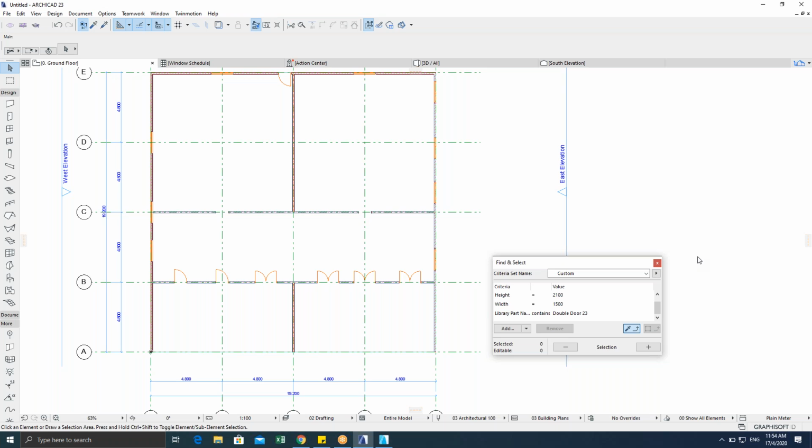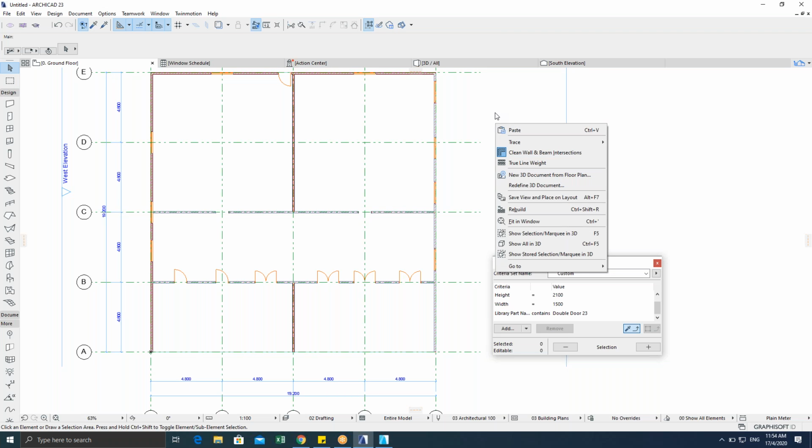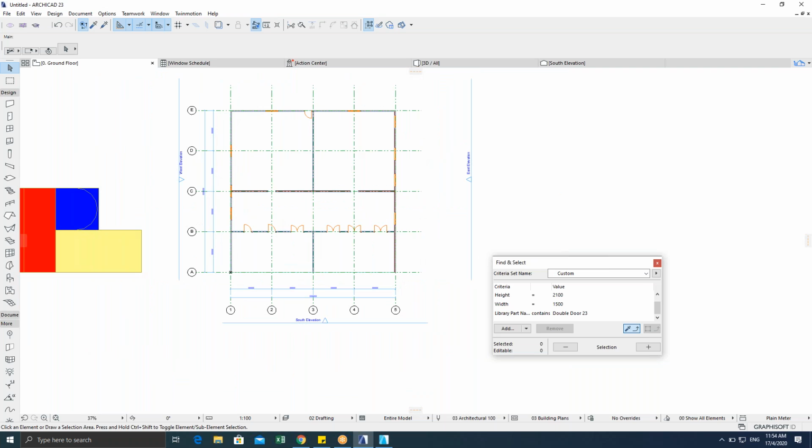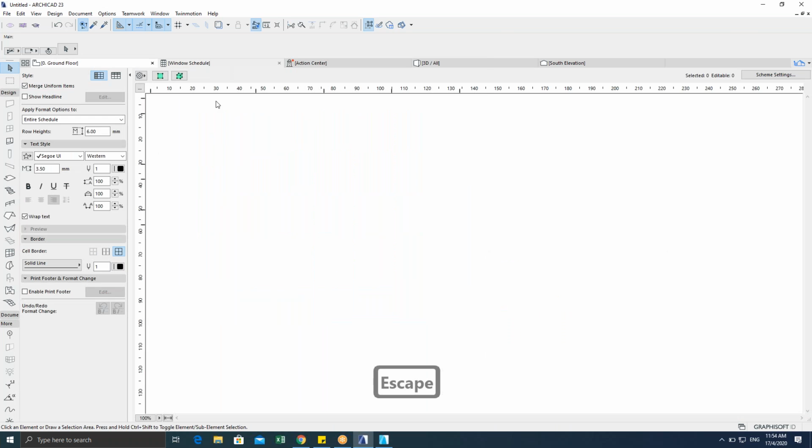Yeah. How about the iron grease? Can we show the list of handles? So with the schedule, handles are normally at a higher detail, and normally the model view options turns these off because it's often too much for an elevation. So we would just need to modify the model view option to create one that is more detailed, that actually shows the handles. And when you're looking at the schedule, you would then use this more detailed model view option. Yeah. Okay. Thanks, James.